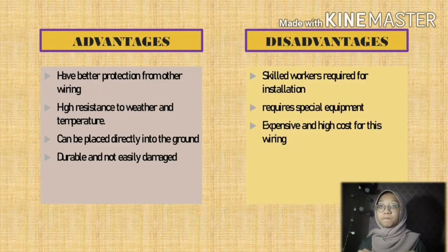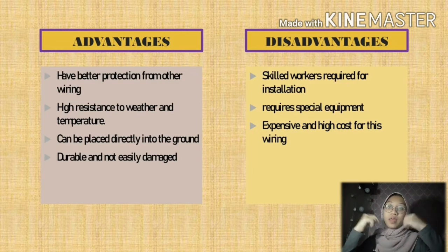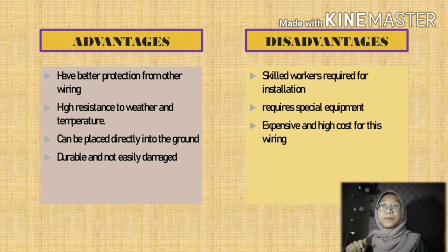Advantages: better protection than other wiring, high resistance to weather and temperature, can be placed directly into the ground, durable and not easily damaged. Disadvantages: skilled workers are required for the installation. It requires special equipment and it's a bit expensive, with a high cost for this wiring.